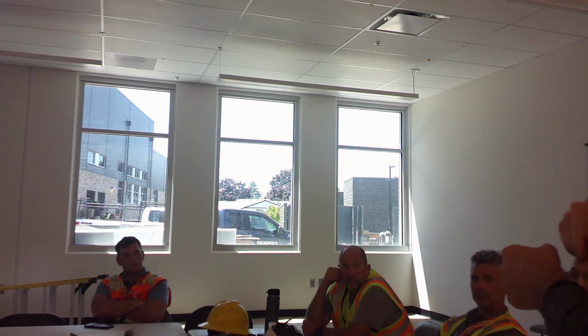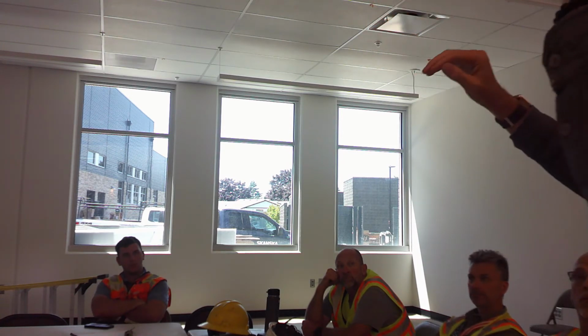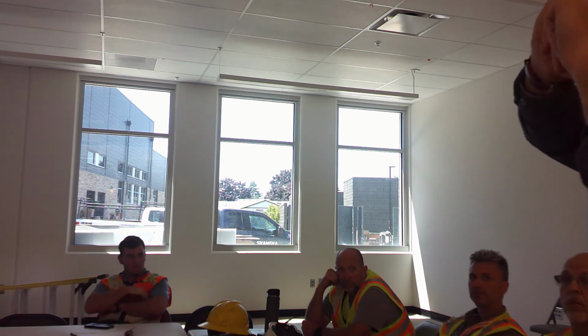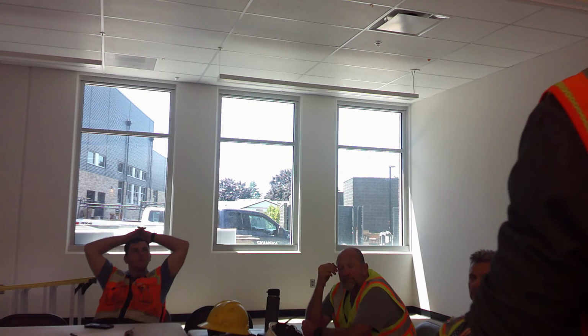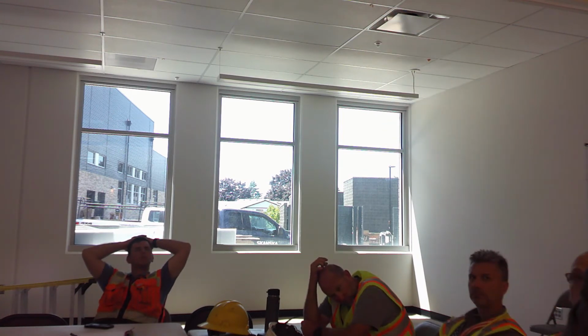That's why you got the 3 controllers with 2 relays each. And so the way those are programmed with the groups, the A side is going to be 1, 2, and 3 for daylight zone 1, 2, non-daylight zone, and B is going to be 4, 5, and 6. So that's typical through all the classrooms.